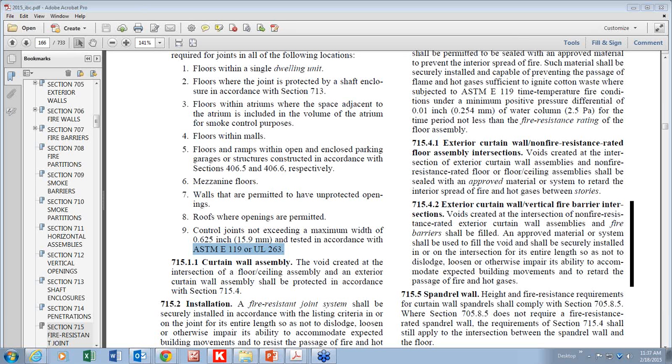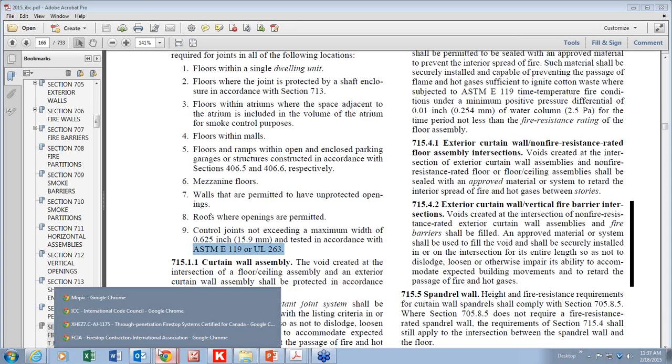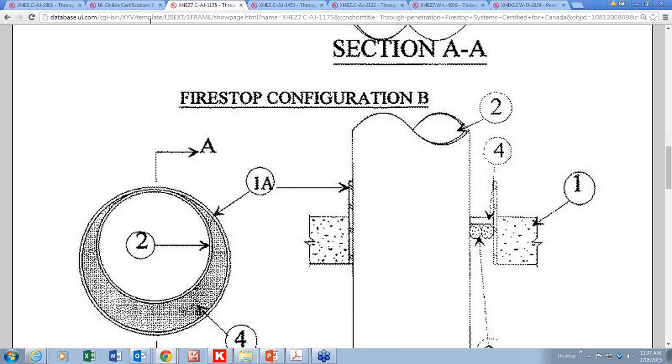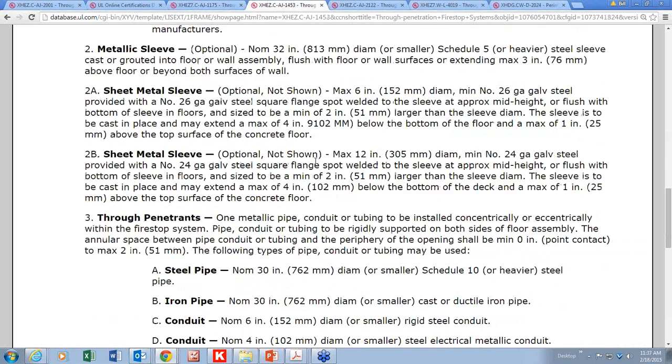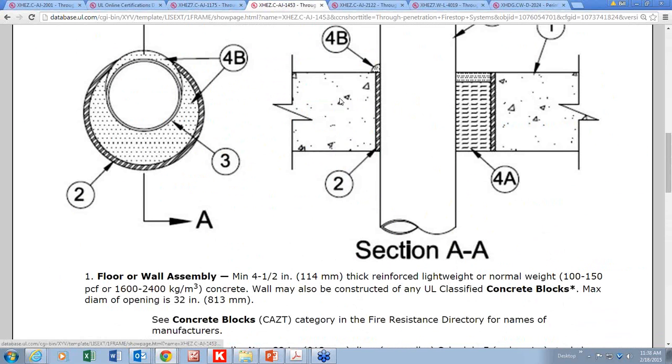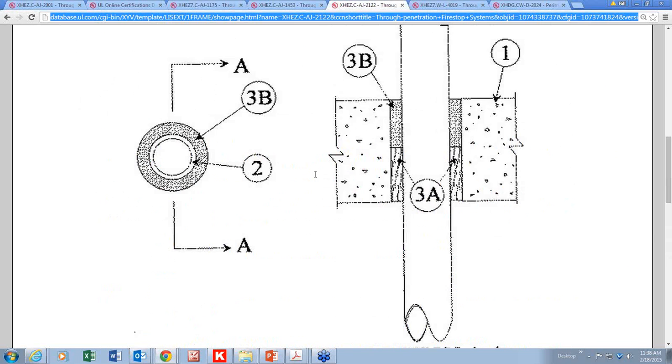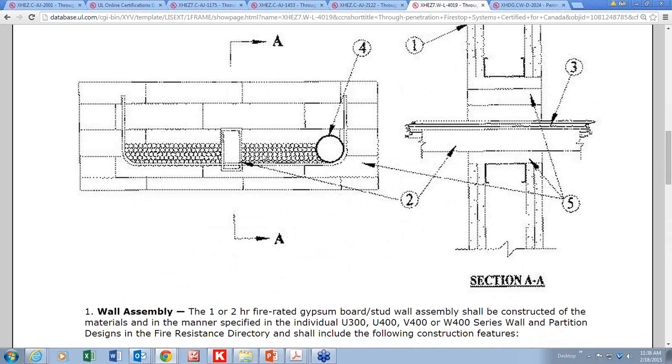If you had stacked bond, you would be basically stacking a fire-resistant brick or block on top of each other, whereas you would stagger the joint by 50% in a running bond if you're stacking them. So they kind of interlock, if you don't understand what I'm saying. Great point, Ron.